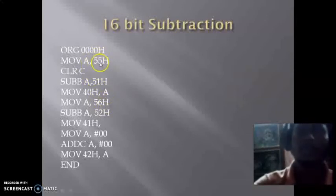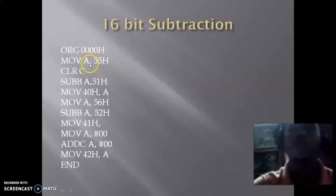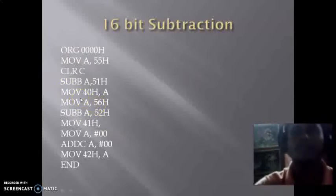We actually store the content of 55H into the accumulator, and we will clear the carry, and then we will subtract the content of 51H from 55H. So we will get the result, and that will be stored into the accumulator. At that time, borrow may be generated, so we have to consider the borrow, and that will be stored into the carry if it is generated. Then the carry will be set as 1. So now the result will be stored into 40H, that is the RAM memory location.